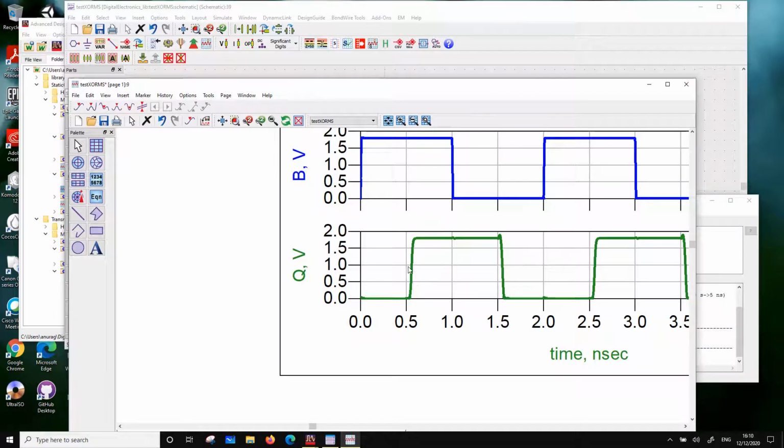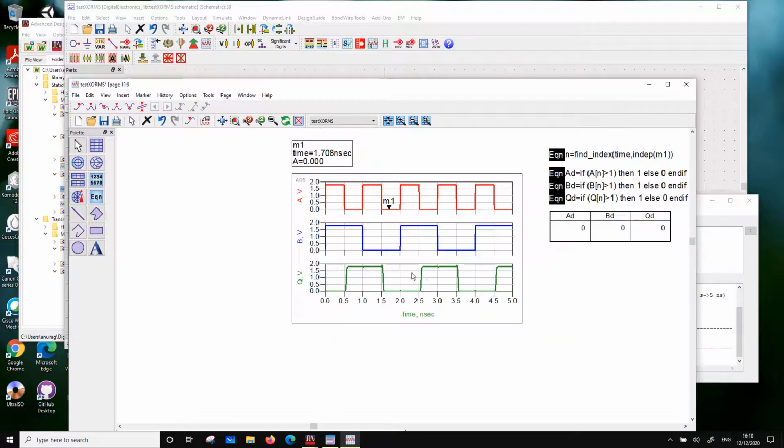So if you were to use this XOR gate, for example, in adders, now there is an additional delay here. If you cascade lots of full adders, then the frequency of operation is limited now. So if you want to use this XOR gate to implement a full adder, you have to use the previous version, because this version will give you a delay, and that will limit your frequency of operation.